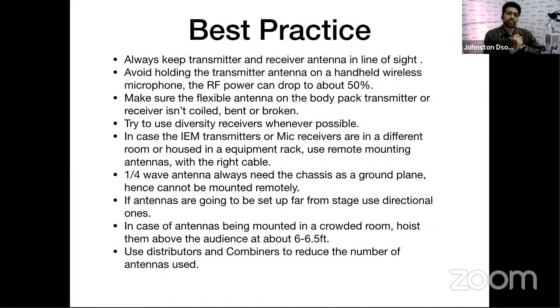Okay, some best practices. First thing I told you, transmitter receiver line of sight required. Avoid holding your antenna. I don't have a handheld microphone here, but what many artists do is they won't hold the shaft of the handheld mic. They'll hold the absolute end where the transmitter antenna is, and once you cover that antenna up, your RF power can drop up to 50%, because your palm is going to absorb all the RF, and then you'll wonder why it isn't transmitting. You're supposed to hold the shaft and not the transmitter antenna.